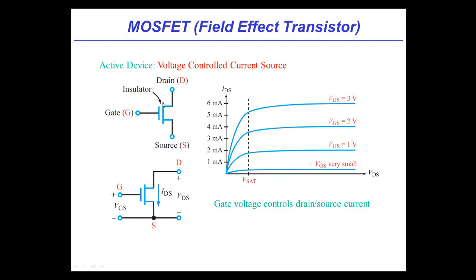Okay, so that's basically what we use a MOSFET for, and it turns out the MOSFET is basically a voltage-controlled current source. In other words, the current that flows between the drain and source lines depends on the voltage applied on the gate. The characteristics are somewhat complicated. It turns out it has various regimes of operation. Specifically, when the gate voltage is really low, below some critical value, the MOSFET essentially looks like there's no current flow. In other words, it looks like a really high resistance between the drain and source. So that's almost like a valve.